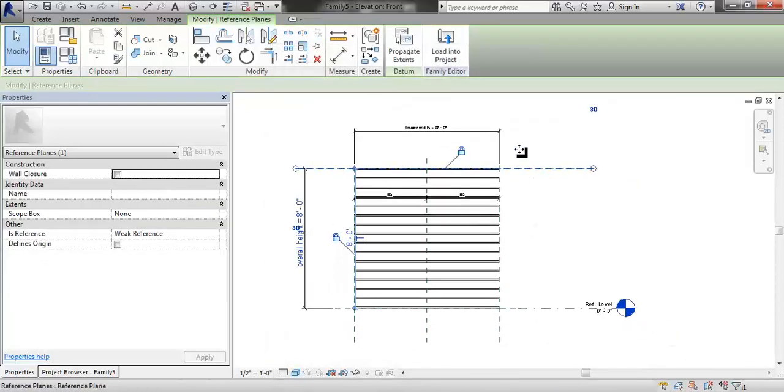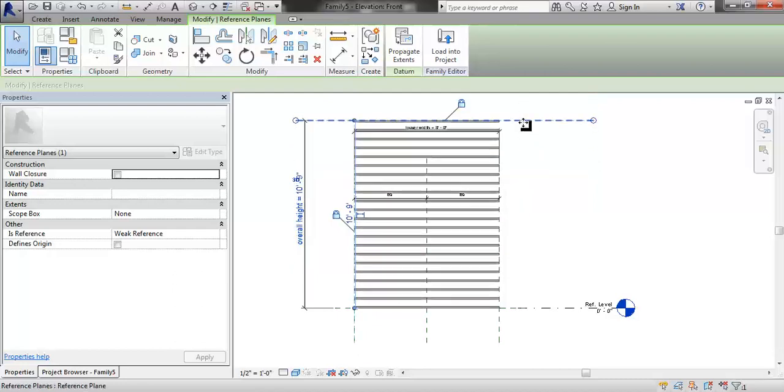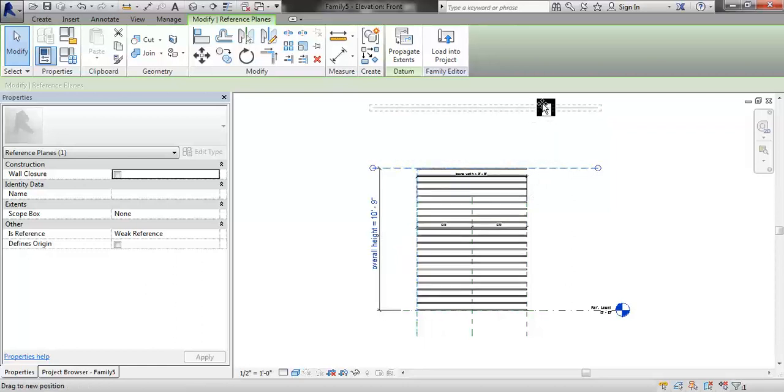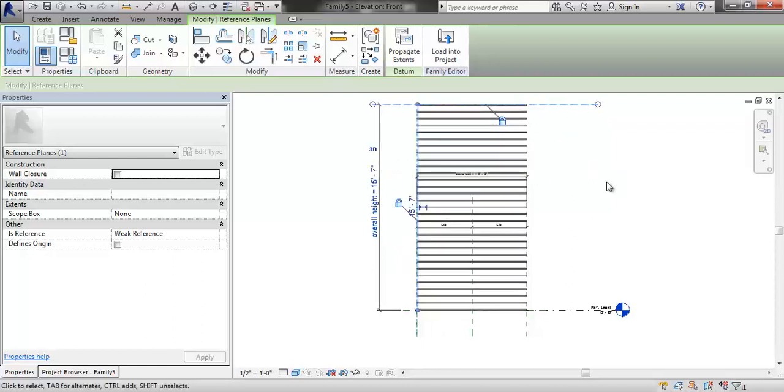So now as I grow my value, it's going to fluctuate somewhat because of the remainder value within it, and we can control that with a rounding function. But as I grow this, it's going to build more and more and contain it within a set boundary of around 1/2 inch. So we'll be between 5.5 inches and 6.5 inches for our spacings before we add a new louver. So that's our parametric louver system.